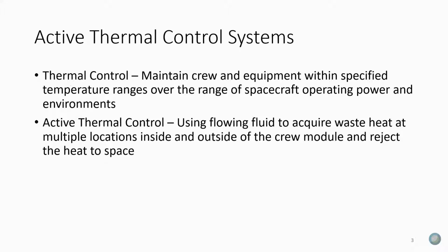When we talk about active thermal control systems, thermal control is a big area, and of course here we're at the Thermal Fluids Workshop. When we're talking general thermal control, we're trying to maintain crew and equipment within specified temperature ranges over the range of operating power and environments. More specifically, when we talk active thermal control, we're talking about using flowing fluid to acquire the waste heat.